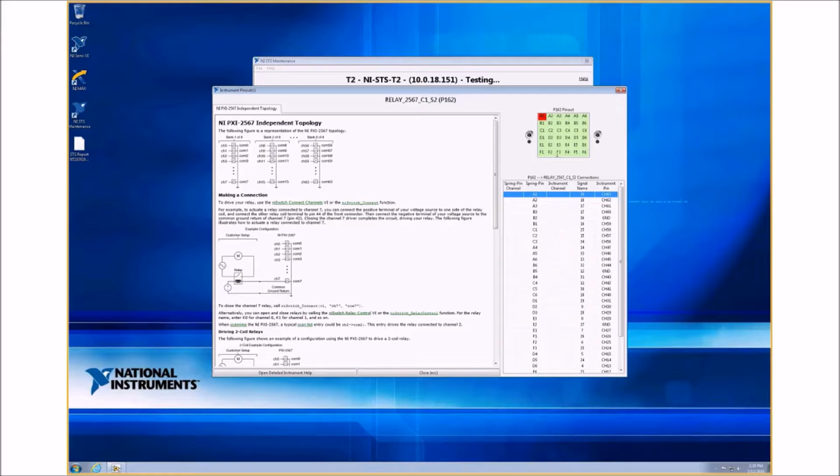And those are really the three things in the path all the way up to the top of the load board that you can change out. You can also try a different checkerboard if you have one of those available as well. So again, like I mentioned, the easiest thing to do is to replace the pogo pin. So I'm going to do that now.